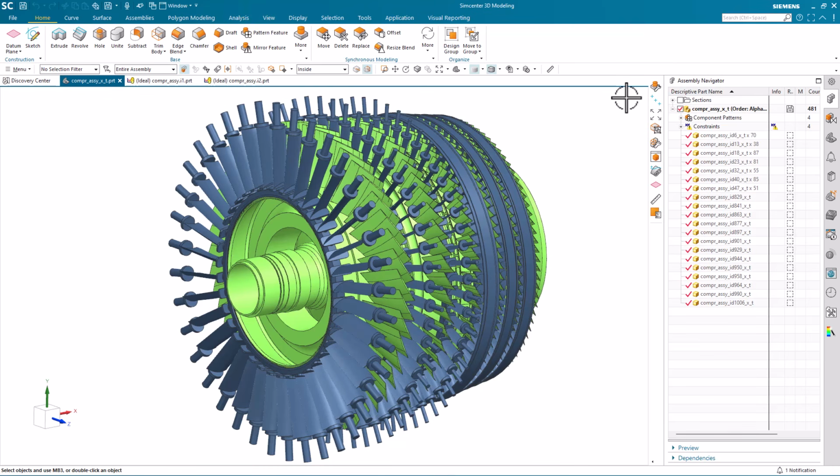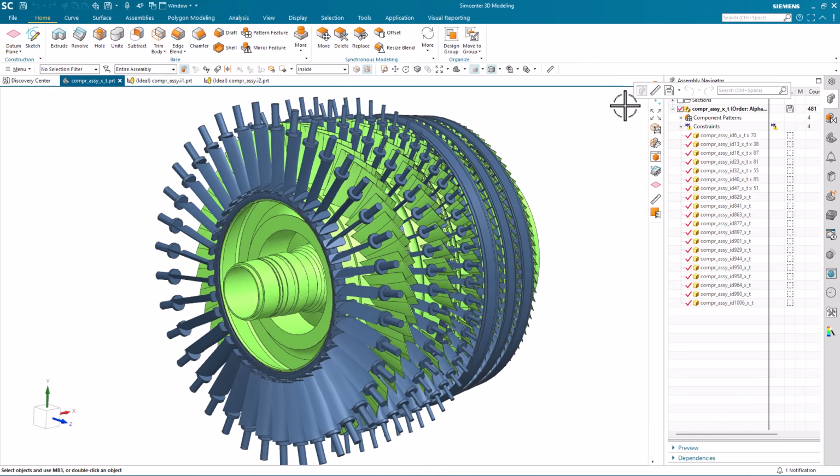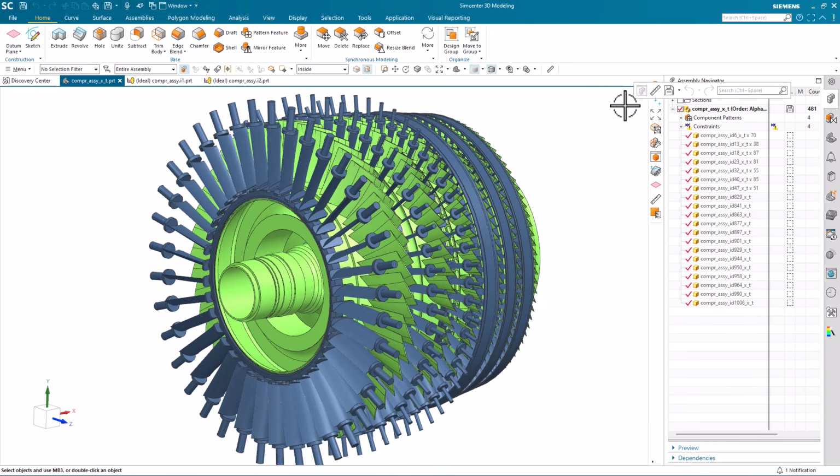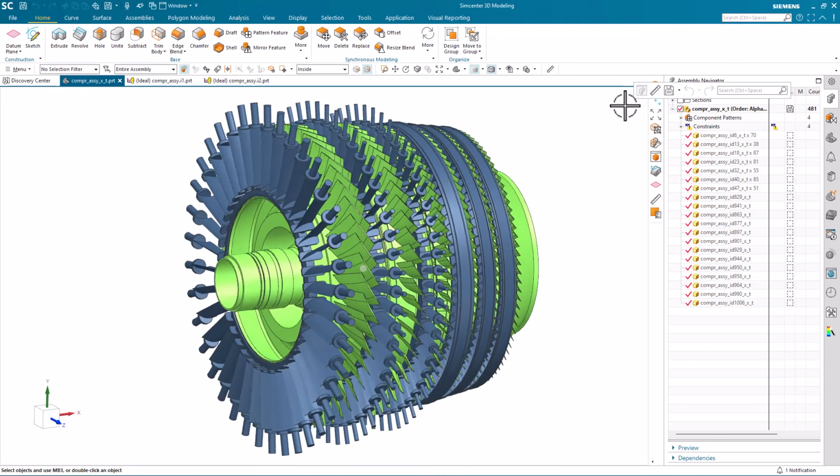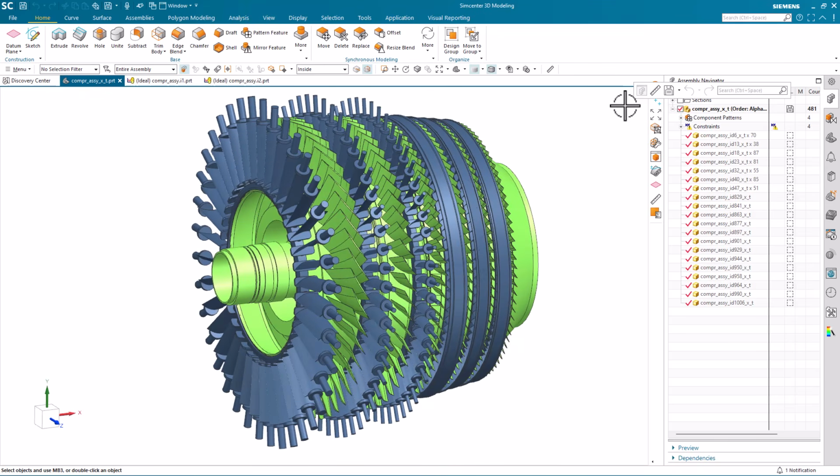It then represents those boundaries as shared faces across solid bodies, exactly like mesh mating conditions. The result is a more robust process and simpler user experience with respect to creating contiguous meshes across solid bodies. The intent with this model is to generate solid meshes on all the components of this compressor assembly. It is comprised of 480 solid bodies. Some of the solid bodies are just touching one another, some are intersecting.